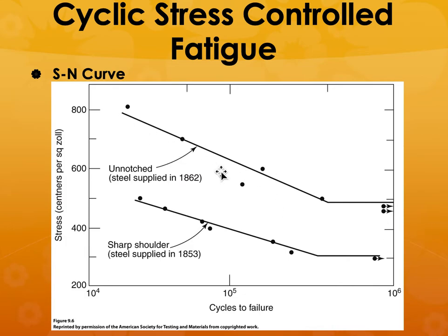So if there is no notch and there are no sharp stress concentrations, that means the component can withstand much higher stresses for the same number of cycles to failure. So if you have a notched versus unnotched sample, what can you say for the same stress level?